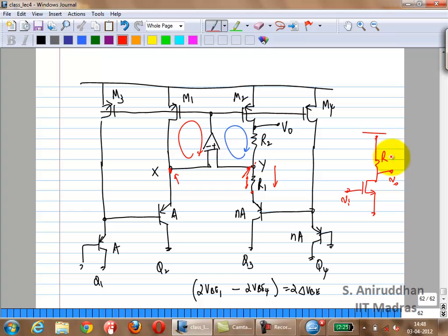Let's assume that the resistance is constant with temperature. I am plotting the gain of the amplifier as a function of temperature. The input has some bias also, so it's VB plus VI. The transistor has a bias current. Let us say that bias current is constant for now. It will decrease. Why?